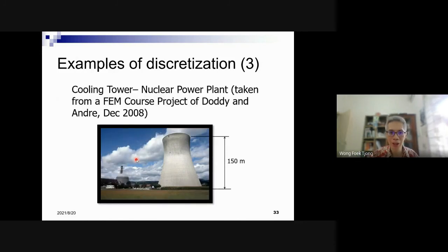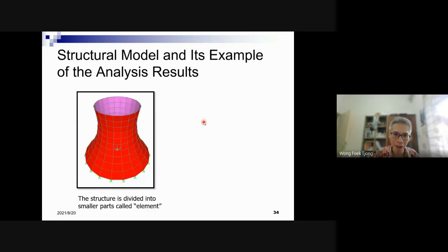Example, maybe I have presented this in my presentation in the workshop. Did you attend? This is the same example, right? For example, if I have a structure like this, a cooling tower, very tall, and then we want to know the behavior, we use shell models like this, and then we create the mesh in SAP2000. This is the possible mesh that we can create, and then these are the supports. The supports are only at the nodes.